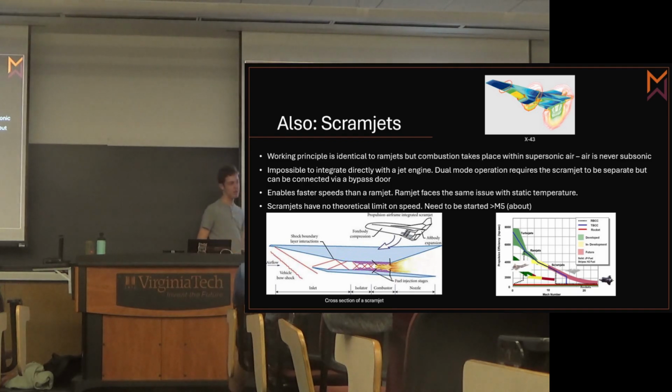And then scramjets are just the next step, the next logical iteration. Because I'm still having all these shock waves, I'm still going to use them to compress our air, I'm still going to burn it, but never subsonic. You'd have more issues in lighting it because I can't have large regions of circulating air. So actually a lot of the ramjets that I've seen, they don't look like these nice images where there's a clean flow path where I can go right through here. The ones I usually see flown are an intake, and then they stop completely and go into some pipes, and into a totally separate combustion chamber where the air is just not moving very fast. But this, it's right through.